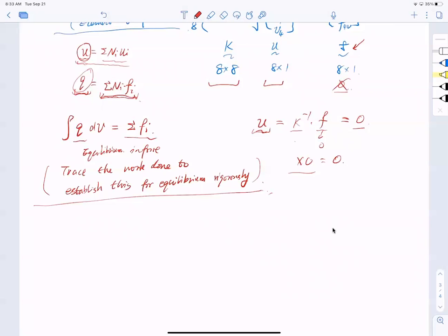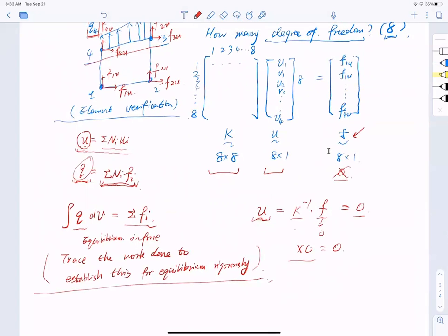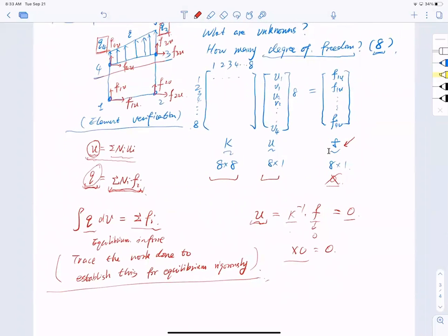But I have a question, Doctor. Go ahead. I understand now, if you want to get the force in the element 4-3, we can multiply the stress by the cross section. The cross section is constant, right? That's a good question, but think about it. When you have stresses exerted on sides 3 and 4, the displacement of 3 and 4 will change because you're stretching it, isn't it? Yes. So when you change the nodes, you change the area of the element itself, isn't it?